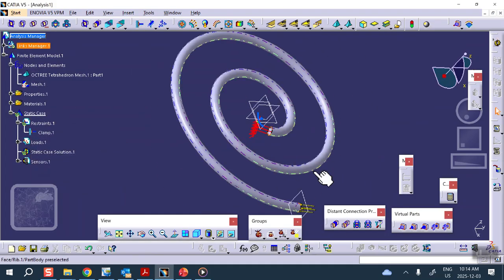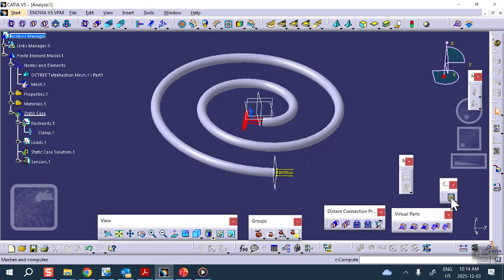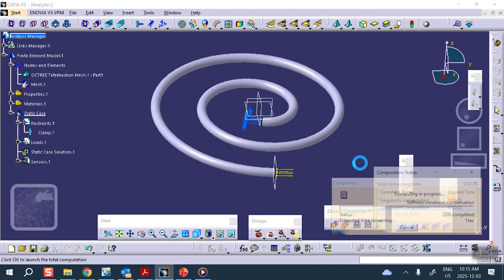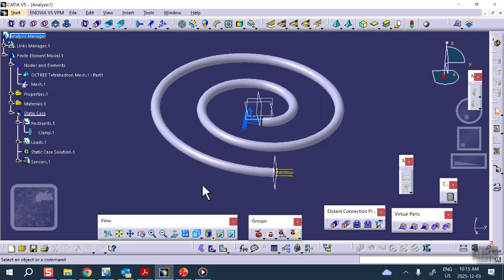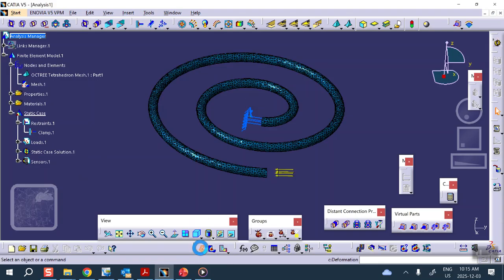Now we're going to put a surface slider on the other end. I can slide there. Obviously, it's not fixed. That's why it says factorization error. So we're finished. Now we can look at deformation. There's a deformation, and then you can animate it.